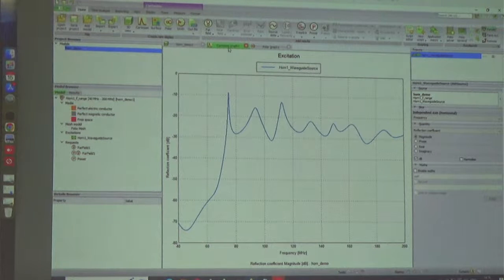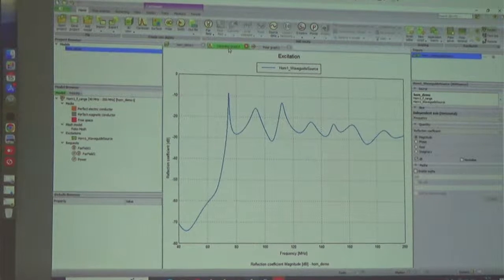The problem arises because of these features. So there is an absorption at 100 megahertz. You don't want it. Because if you miscalibrate this, you might end up producing absorption features in your data that are not related to your cosmological signal, but to your antenna itself. So spectral features in your S11 directly translate to spectral features in your observations. And of course, we can try correcting for it. The question is to what accuracy you need to do that.